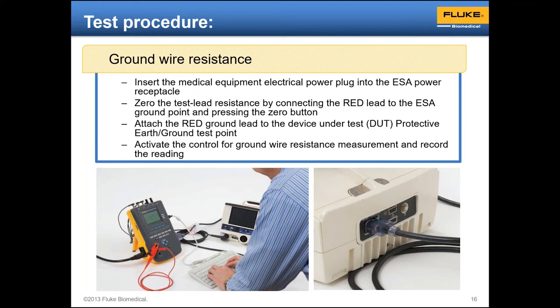So we're going to make sure that we look at the resistance and make sure that it is as close to zero as possible. And I apologize if I didn't explain that exactly yesterday, but it is always the case, no matter what category of medical device we're testing for electrical safety. We will first always make sure that that ground wire resistance is appropriately low resistance.